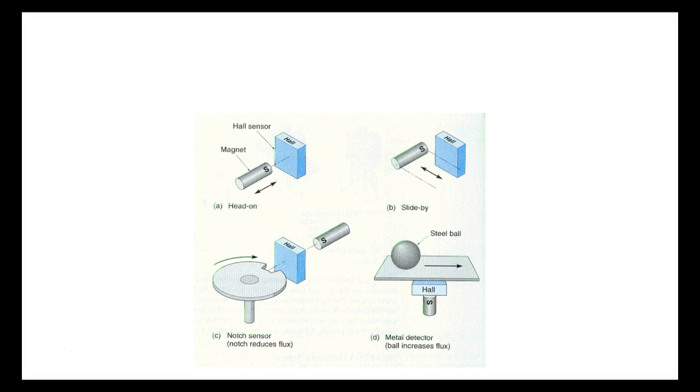No, well, it's causing it to become true. It's causing it to go true or false. There is no switch in it. You're holding that thing in your hand, looking at it. That's not a Hall effect. That's a reed switch. A Hall effect is an electronic circuit. It's a 3-wire sensor and not 2-wire. That's a 2-wire sensor right there. That does not have to be powered up.